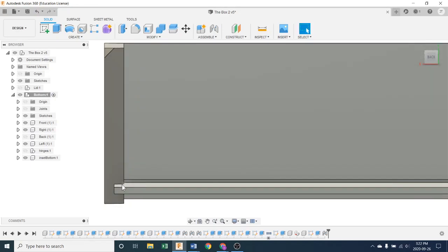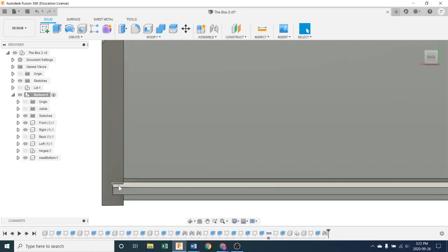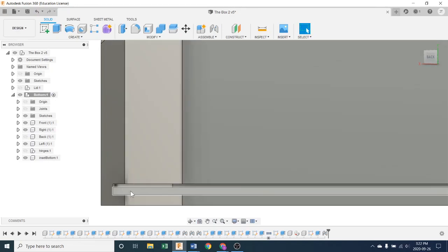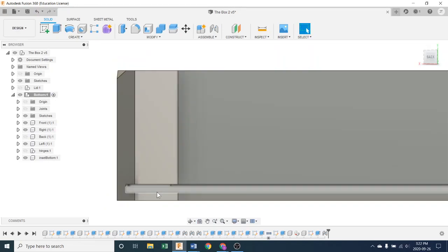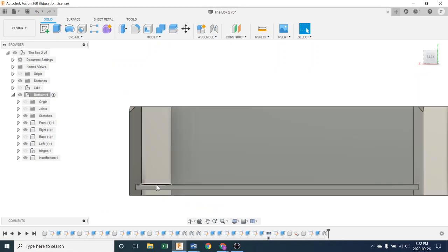I mean, our bottom is supposed to float from a woodworking perspective inside the groove we make. Now, we're going to make our groove custom sized for the actual bottom. It shouldn't be tight. Now, if you wanted to see it nice and fit well, obviously you'd have to make your groove, your slot, sorry, a little smaller, or your bottom a little thicker. But we'll work on what materials we have and how good a joinery we'll do when we actually make it.